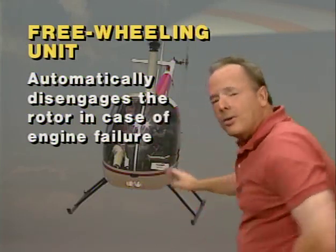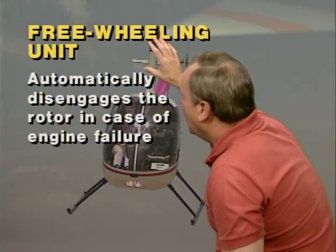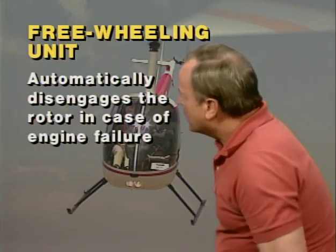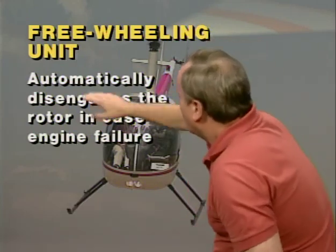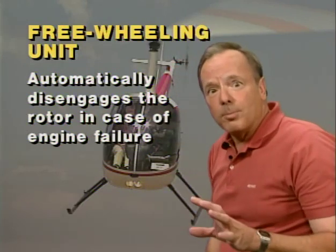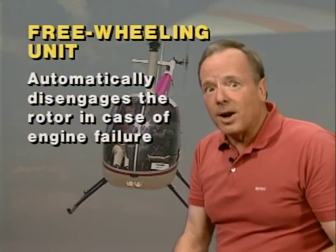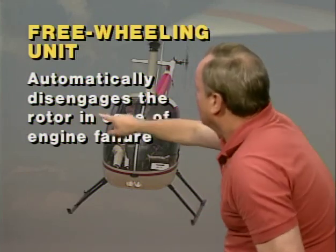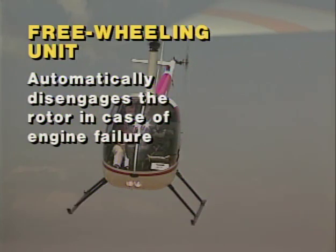Now, they're going to ask you on the test, why do you have a freewheeling unit? And one of the things they'll say is to reduce or relieve the starter load. No, that's not correct. You have another clutch for starting the engine. The purpose of it is to allow you to be able to fly the aircraft in the event of an engine failure and to keep the rotor RPM up. Now, they'll also say so you can practice autorotations. Well, it's true, you can practice autorotations, but that's not the purpose of it. The purpose of it is to disengage the rotor in the event of, and terrible thought, an engine failure.